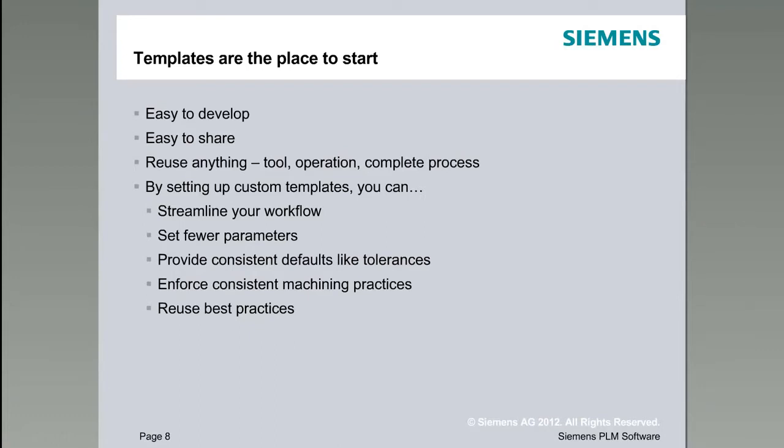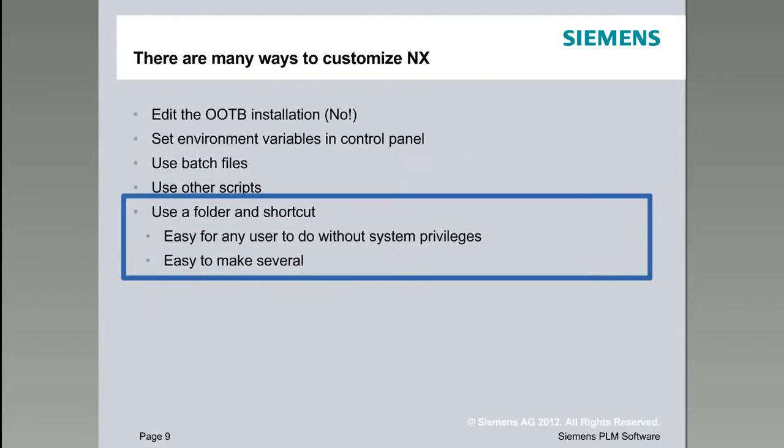And through using these process templates, you can enforce consistent machining practices. So everybody roughs with the same stock, followed by finishing with the same amount of step over, whatever you want to do. So it gives you a pretty good way to do this, all without doing a whole lot of code. So really a good CAM programmer can go in and do templates. So this is why I think this is a really good place to start. As far as bang for the buck goes, it's a really good investment.